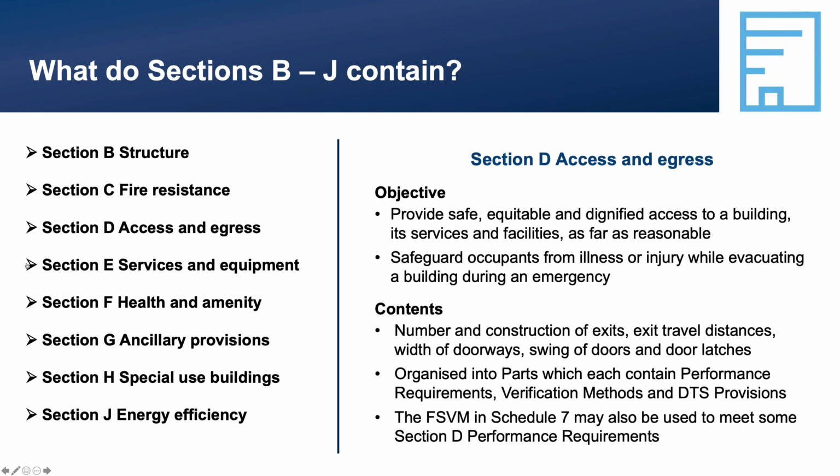The premises standards were developed to address the gap between building law and the DDA and to provide certainty in relation to what level of access to public buildings would satisfy the general non-discrimination requirements of the DDA. This results in a uniform set of requirements that both apply in relation to non-discriminatory access under the DDA and in relation to the requirements for access that must be complied with in order to obtain a building approval under building law. The premises standards were reviewed in 2015-2016 and amendments were made to the BCA in response to this review.